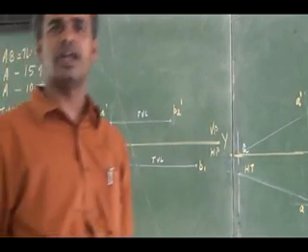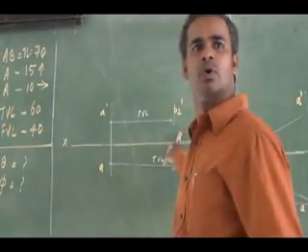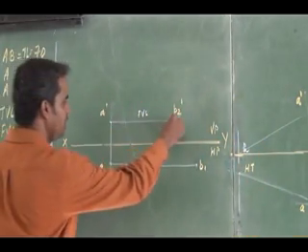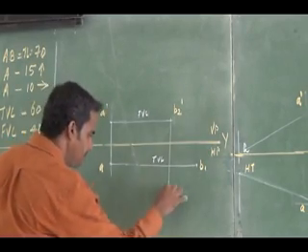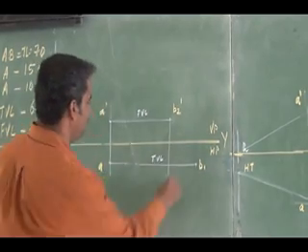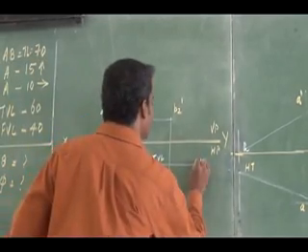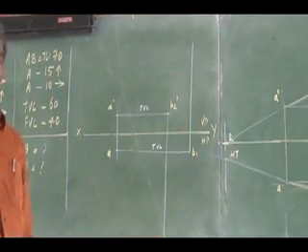How can I proceed to find theta and phi? I can draw a projector line for these two ends vertically downwards. Similarly, from end B1, I can draw a projector line vertically.